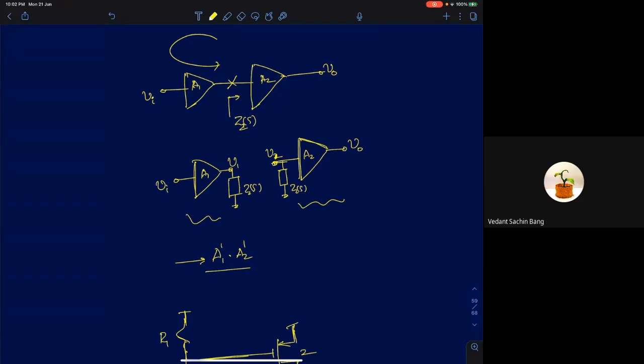But right now, I'll just finish off our discussion on finding the loop gain in negative feedback systems. What we said was to find one node where the looking-in input impedance is infinity, break open that node and apply a test voltage. Find some node where the input impedance is infinity, so that the current drawn inside is zero. Break the loop at that point, apply a test voltage delta V, traverse the loop and return back to this point.